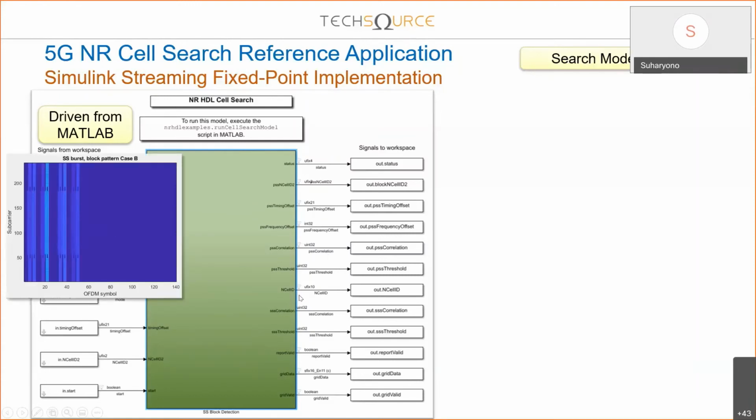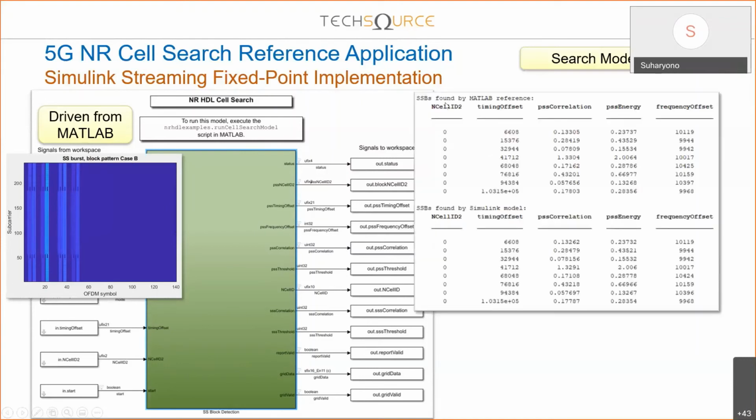This verification step is typically important, so you can see what the effect is. You can see on the right side how we can verify this particular algorithm with a MATLAB golden reference. We can observe the latency and the quantization effect from this fixed-point architecture that is being introduced.